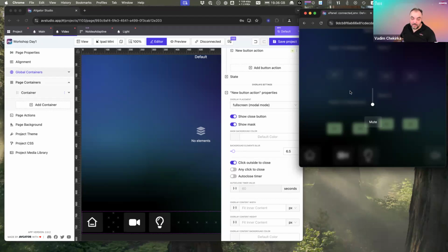I'm sorry. But what I would like to tell you, try not to use too many filters and blurring on slow panels. Crestron touch panels are really not so powerful for such visual effects.